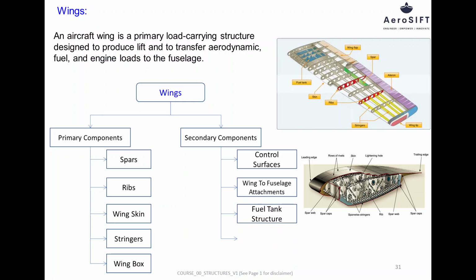In many aircraft, the wing contains integral fuel tanks formed within the wing box. The fuel tank structure includes sealed skins, spars, and ribs that safely contain fuel while carrying structural loads. These structures must withstand internal fuel pressure, thermal effects, and sloshing loads during flight and maneuvers.